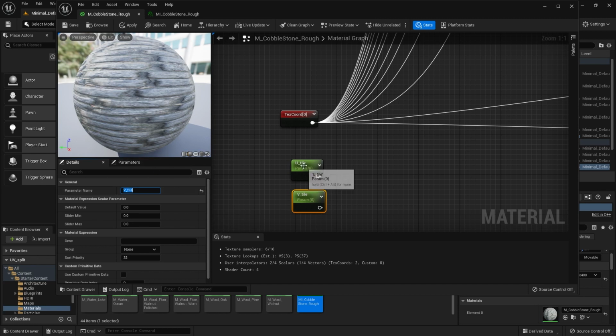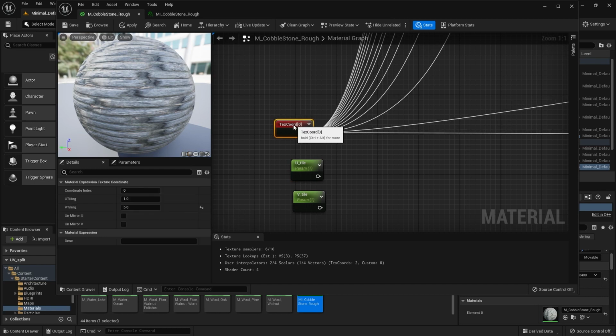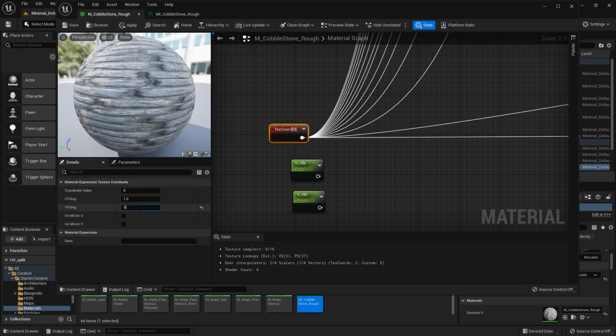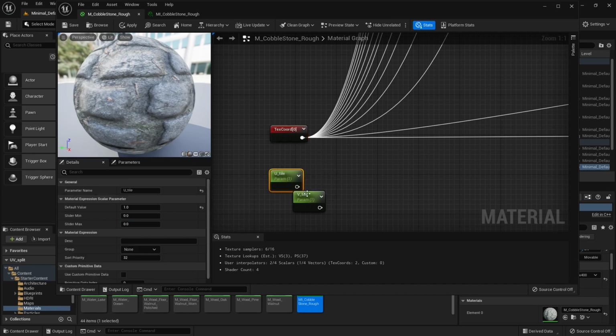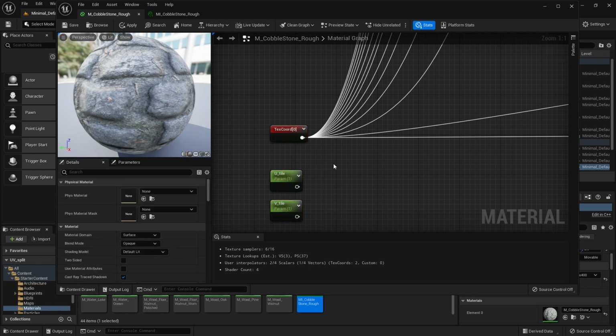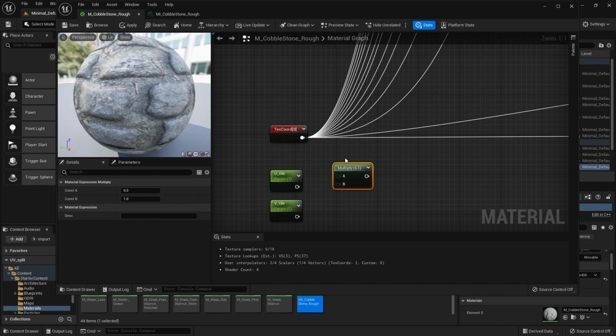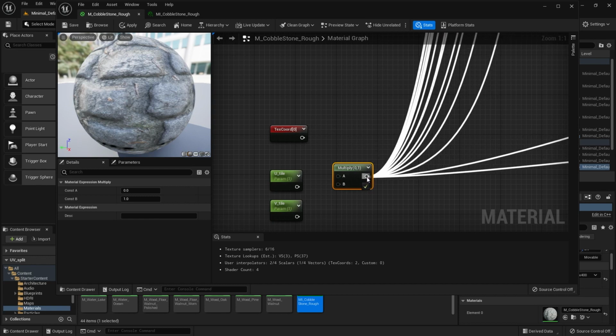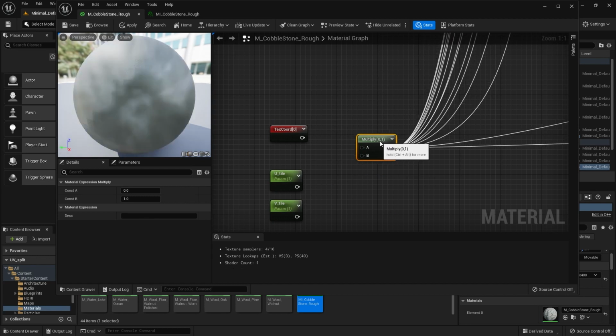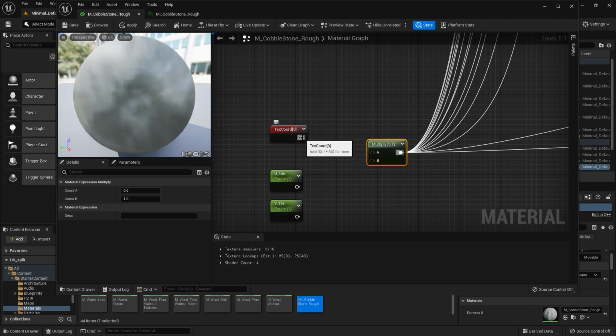All right, so here's our values, and let's just default each of those to 1, so our initial difference we won't notice. We still want to keep this original texture coordinate, and let's set this back to 1, its default value there. But we want to be able to modify these two values by these two parameters as a multiply. So hold M and click to get a multiply node. And if you hold control, you can control drag that entire chunk there and plug it in to the multiply. And then we have our original texture coordinate U and V values going in here.